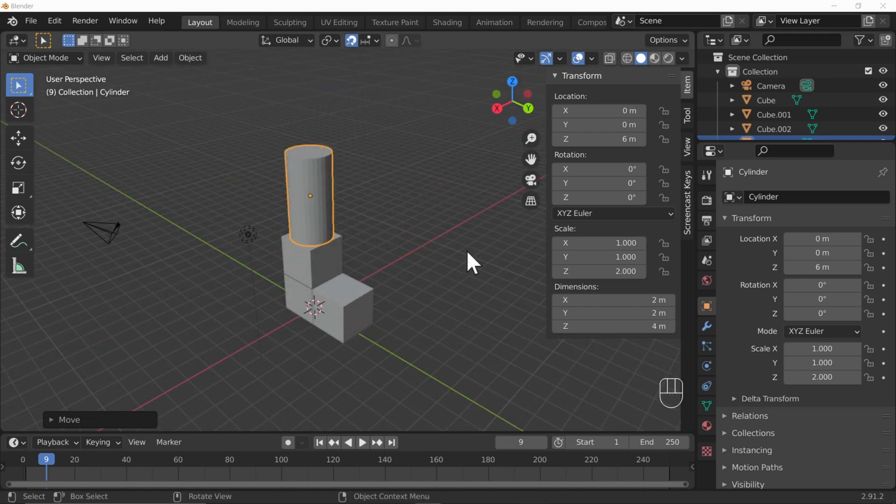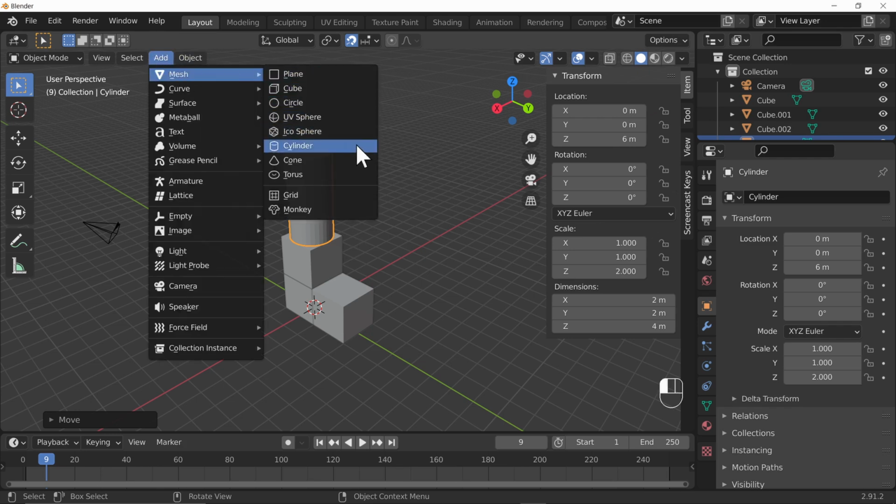Okay, so that leads us nicely onto a challenge. I'd like you to play with snapping and create yourself a little building. It doesn't have to be anything fancy. I just want to see what you can create by just moving some of these primitives around. You don't have to use just the cubes. You can use cylinders or whatever you fancy under this list, under the add mesh menu. Any of these, just put them together and see what you can make. And make sure you've got snapping turned on so you can really position things perfectly. Pause the video now and give that a go.